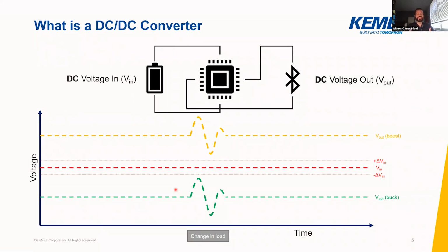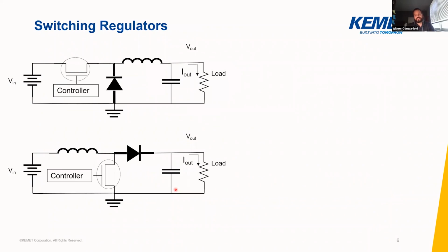Now, the regulator is allowed a moment of adjusting to that load, but a good regulator minimizes the settling time and the related overshoot and undershoot of that change in load. And this is the so-called transient response of a regulator. Now, these regulators come in many different topologies. This is not the exclusive and only list of different regulator topologies, but those different topologies work in careful concert with the passive elements that are related to them.